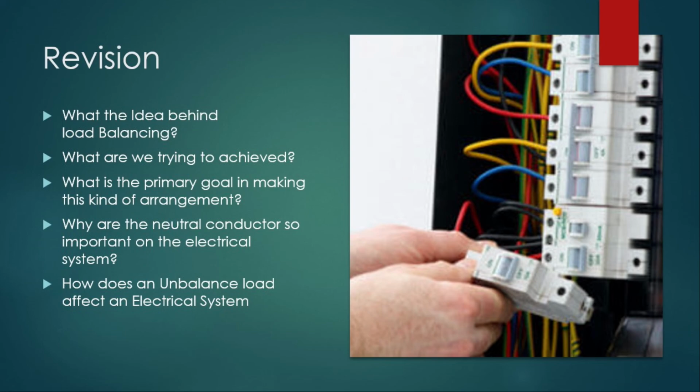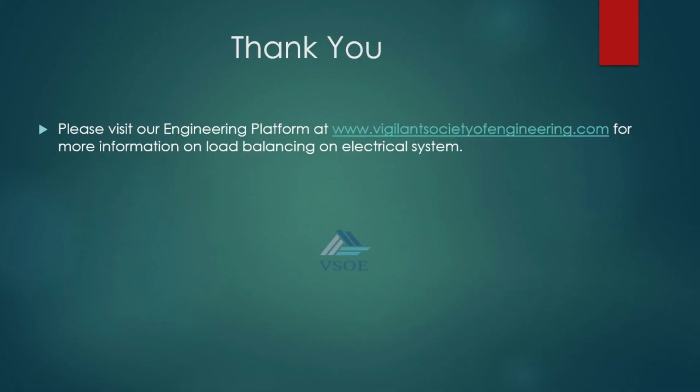So you want to distribute them evenly, so that when the current is returned back on your neutral, it is extremely small and the neutral can really handle the amount, since we said that there are multiple phases and just one neutral. So we balance our loads in order to create a safe system of operation for our electrical circuits. It's just that simple.